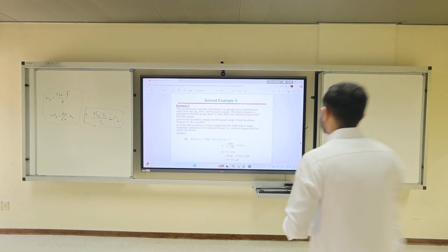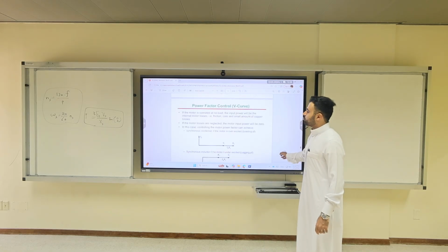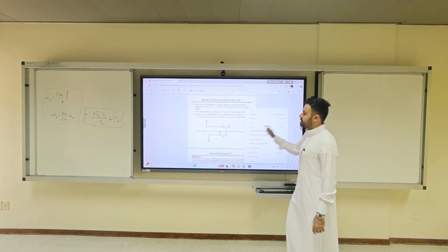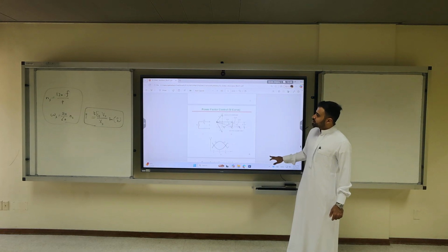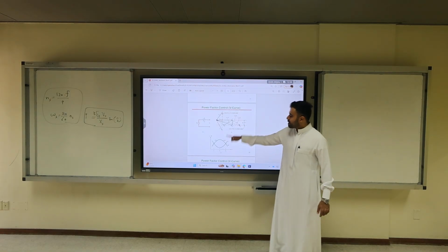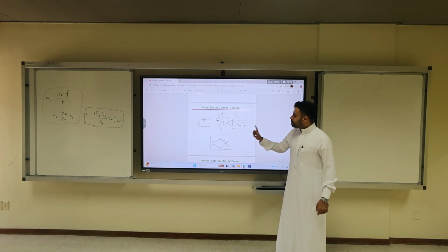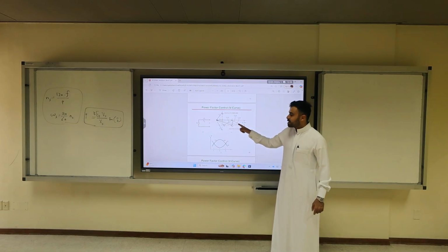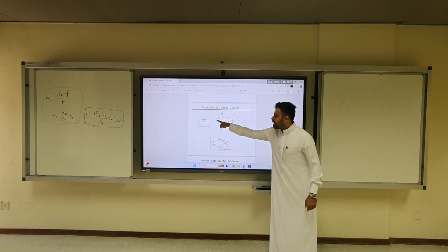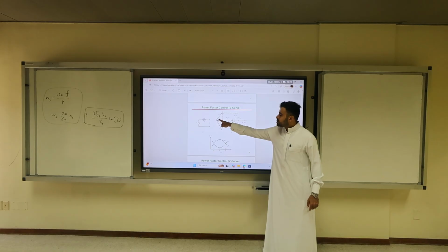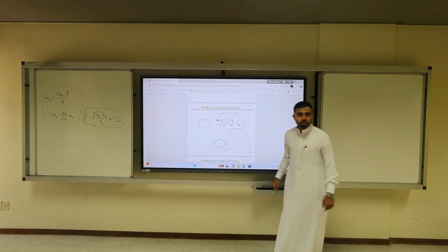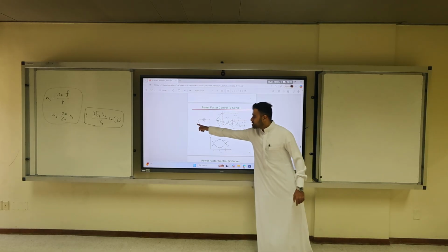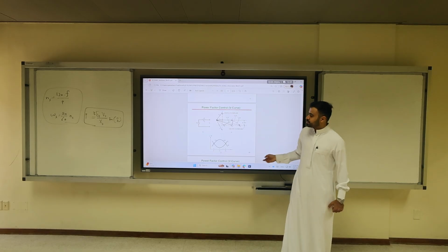Today we will continue our discussion regarding the condenser, and what is the job of the condenser and the synchronous inductor to improve the power factor. If we note from the power factor control, or what we call the V curve, by just changing the excitation voltage I can control the magnitude of the armature current, and the angle of it with respect to Vt. So I can have Vt Ia control by just changing the excitation voltage at this bus.